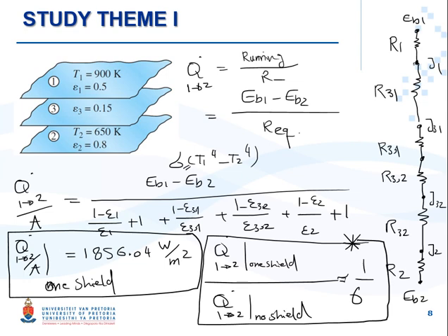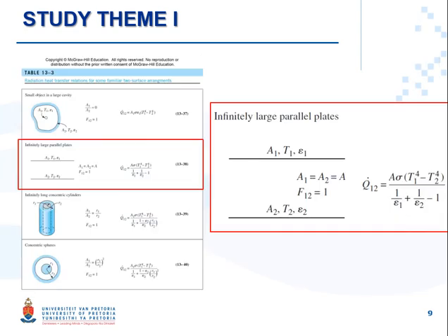It decreases the radiation significantly. But the other thing is, it looks very simple. Is there any easier way to do it? Yes, of course. There is table 13.3 I just showed you previously. It's for some very standard or famous two-surface arrangements. You can use those equations inside the textbook. You don't need to do anything, you can just refer to it, saying I'm using this equation, for example 13.38 or 13.39 from the table, and you will be fine.